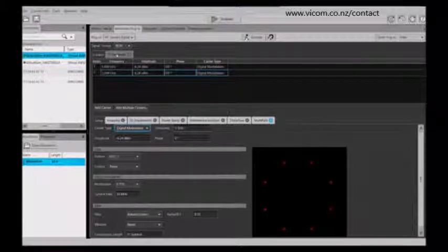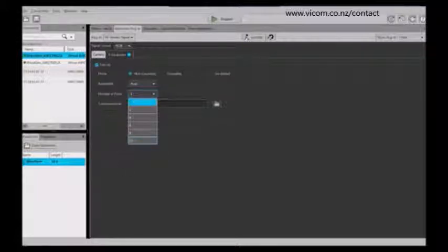The other thing you can do is add S parameters. If you have components in your system and you want to build a waveform that includes those components, you can include the S parameter of that particular component, either from a filter manufacturer or amplifier manufacturer, or you can get it using a network analyzer. So we support up to 12 ports of SP files. So this gives you the flexibility of taking those S parameter files from your components and then embedding them into your actual waveform, so that you don't have to have those components in the system when you're doing your testing.